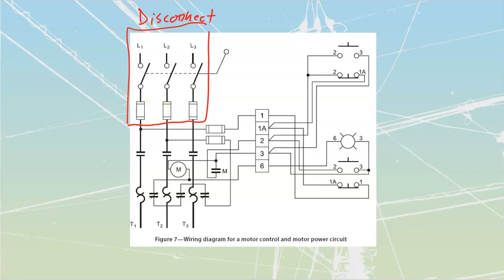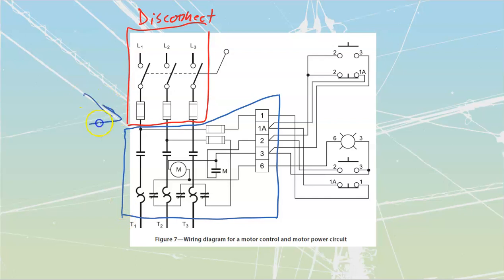Then I'm going to have another box, and inside of that other box, let me just erase that because I cut off a node over there, I'm going to have all of this stuff. There's going to be a terminal strip in a lot of cases. A lot of our NEMA enclosures came pre-equipped with terminal strips. And then we are going to have all of these components. What we see, although it's really tiny in that gap over there, is that there are 3 lines that go from my disconnect over to my starter. That's all going to be power circuit components. Inside of my starter over here, which has both the control and the overload protection side of it, we have 3 lines that go to our motor as well.